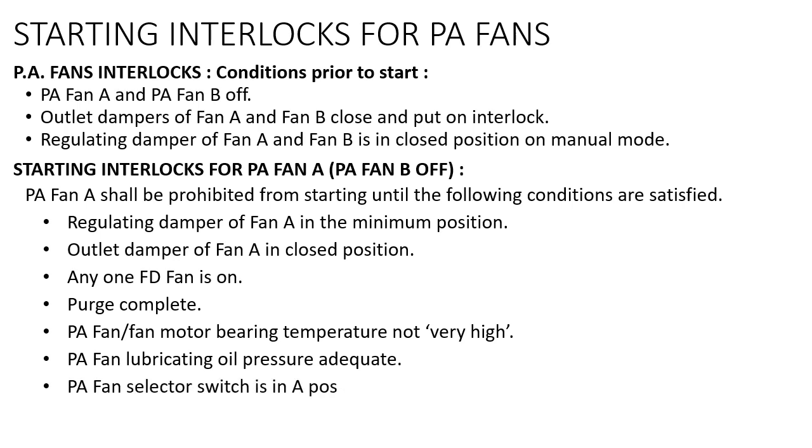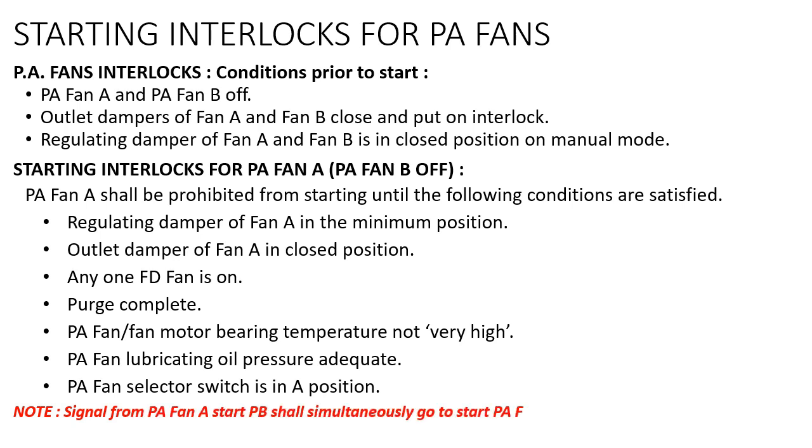PA fan and fan motor bearing temperatures are not very high and no tripping command is there. Then PA fan lubricating oil pressure is adequate. PA fan selector switch is in A position. Note, the signal from the PA fan A start push button shall simultaneously go to PA fan A and the seal air fans. Means as when you give the starting command to PA fan, the seal air fan will also start. So these are the starting interlocks for PA fan A.